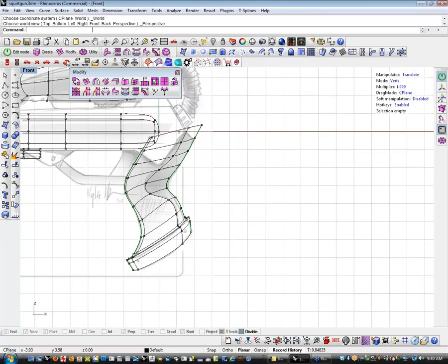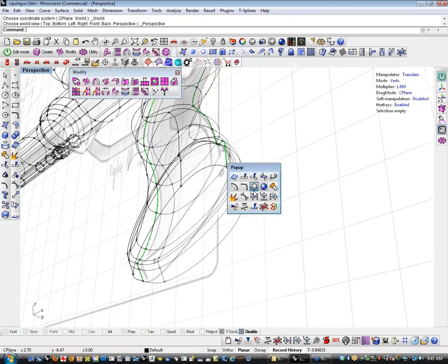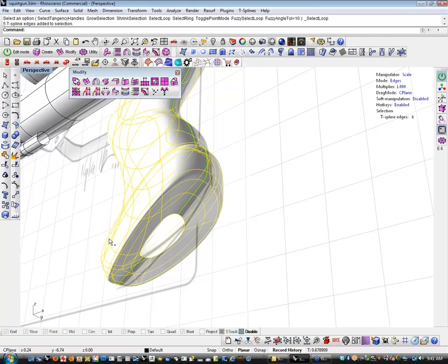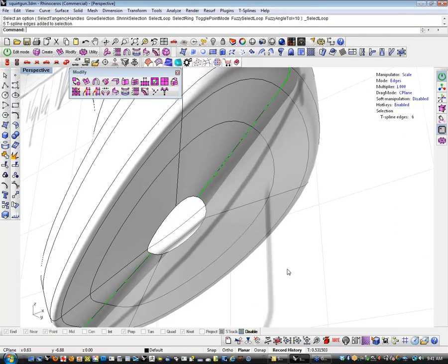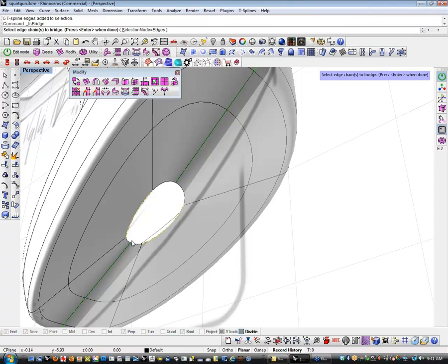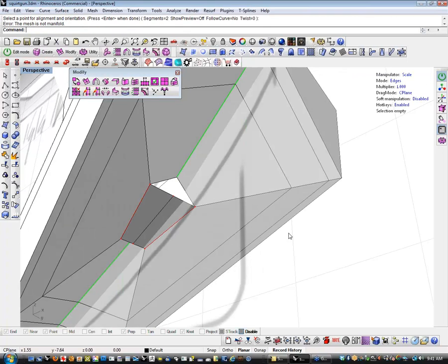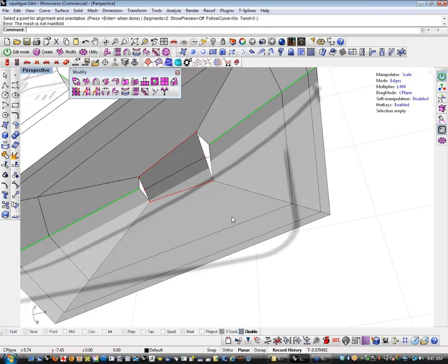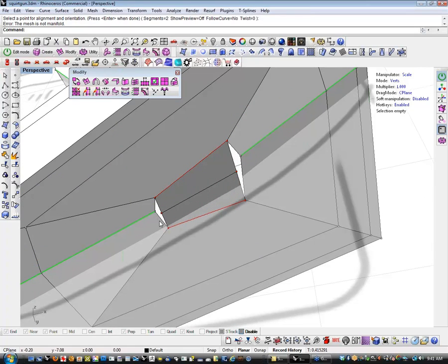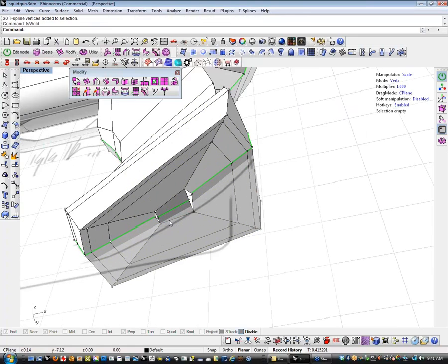So, all right, what are we doing? All right, so let's close the bottom of this up, and we're just going to do that by scaling, Alt-scale, Alt-scale, Alt-scale, and 1, 2, 3, 1, 2, 3. I'm going to pick this, and I'm going to bridge between the two of them using 2 segments. It's going to blow up on me because I bridged with symmetry on. All I have to do to fix that is select these points and weld them.